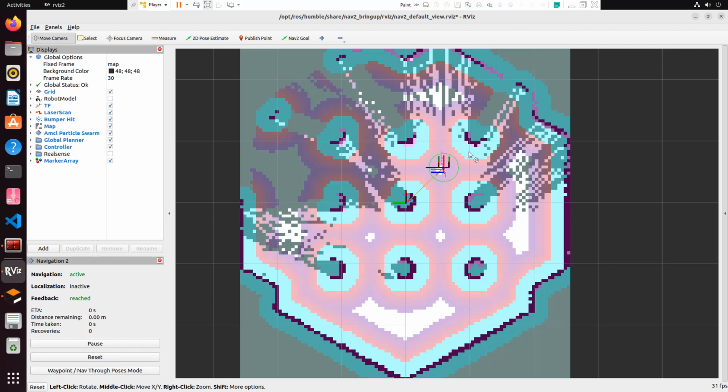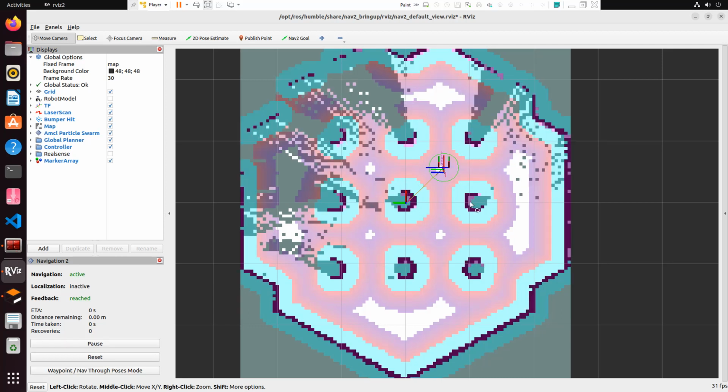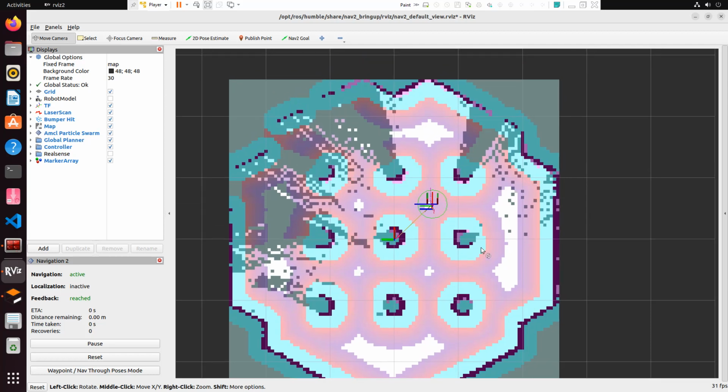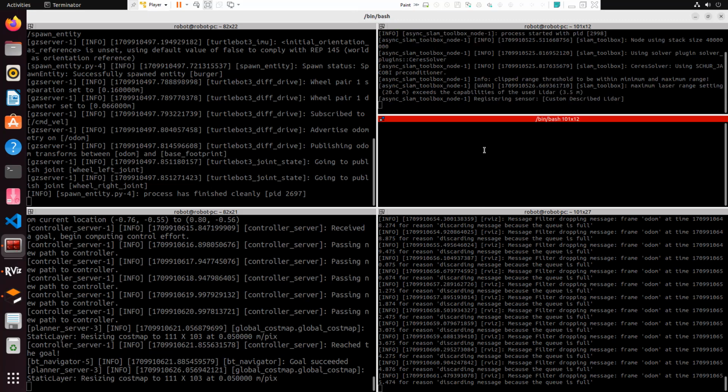I think we have tried this kind of configuration in ROS 1 as well, like running the navigation and gmapping in parallel. If you remember, in order to run the navigation stack you need to run AMCL, right? The AMCL node is for localization. You can do the localization using SLAM as well. Currently we are running the simulation, then the navigation, and then the SLAM. Better will be taking RQT for an understanding, so you will get to know what is happening